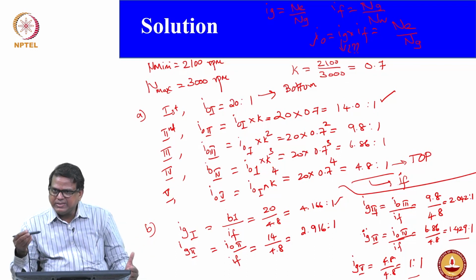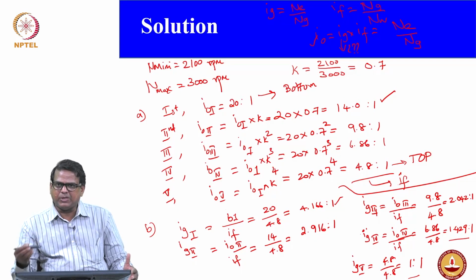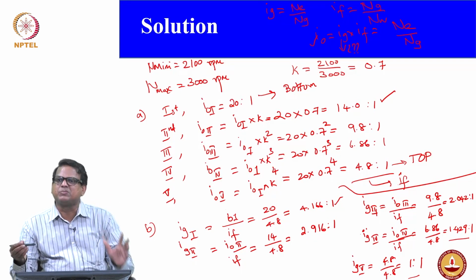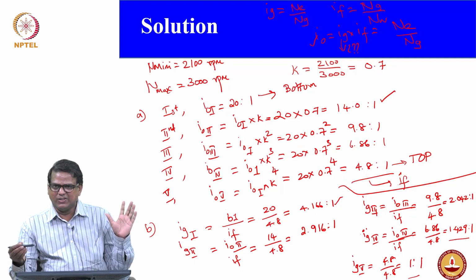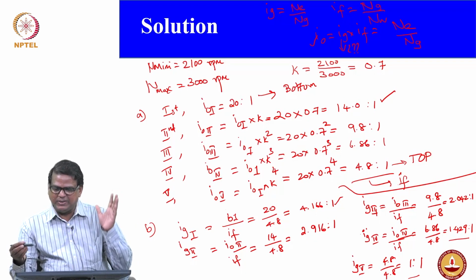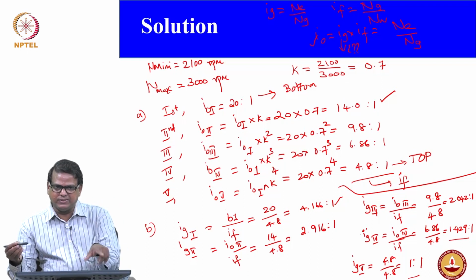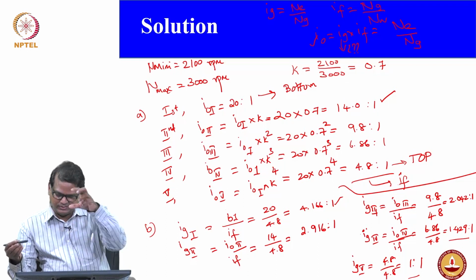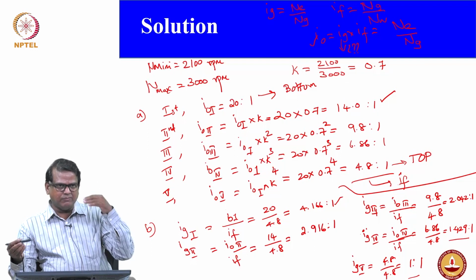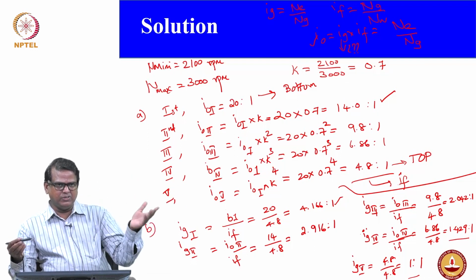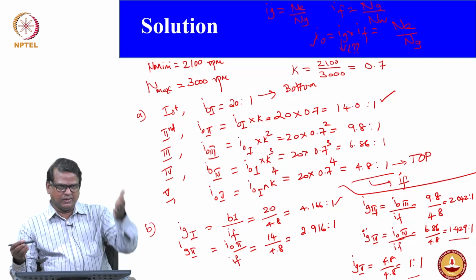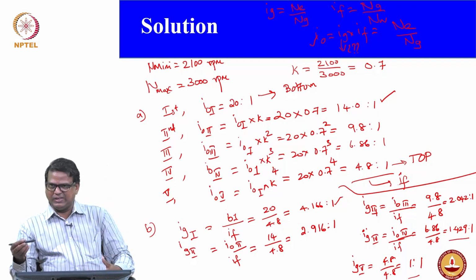Please understand that the purpose of the gearbox is to reduce the speed from the engine speed. So, that is what we are doing. When I discuss the sliding mesh constant, I will tell you. In the video also I have explained that when the motion comes from the engine to flywheel, flywheel to clutch, immediately you have speed reduction to the layshaft.